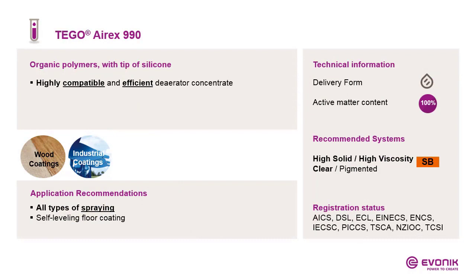TEGO Airex 990 is made up of organic polymers with just a tip of silicone. This is one of my favorites because it is both highly compatible and highly efficient. This deaerator is delivered in liquid concentrate form and is recommended for high solid and high viscosity solvent-borne systems. Because it is highly compatible, it is safe to use in both clear and pigmented coatings.